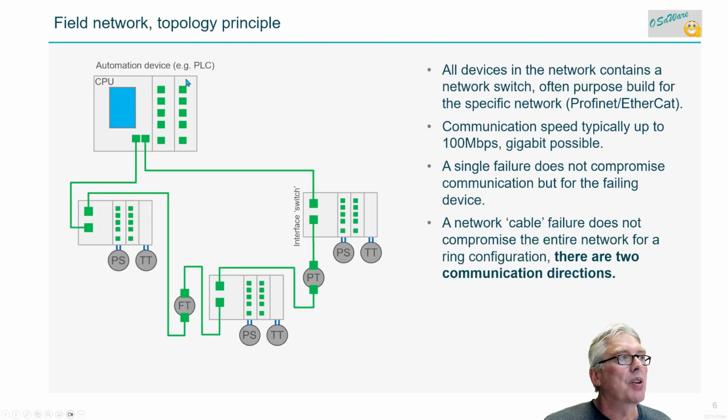And then we have the network interface, let's say 100 megabits is the standard. They can go into gigabits, and it will eventually. OPC UA FX will probably go much faster. But the information you're communicating from sensors is not a lot of data. Here it only shows remote I/O in a redundant ring, where there is a flow transmitter in the ring too, and here you would use switches.